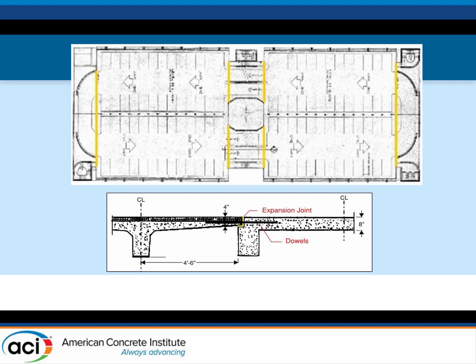What they did that was very unusual is that the precast segments in the middle, it's a single T system and the columns don't line up from inside to outside. So the precast system had no inherent lateral stability. What the engineer did was he put dowels to connect the precast segments to the cast in place. So they transferred all the lateral shear to stabilize and hold the precast system up. They relied on the cast in place segments to do that. Novel idea. Unfortunately, you put all that critical reinforcing through a moving joint.